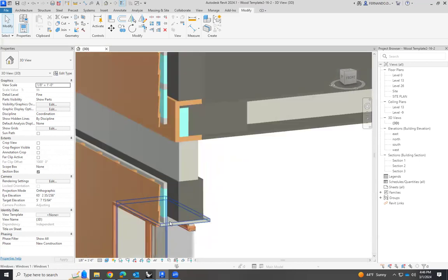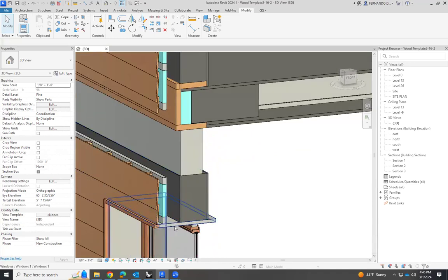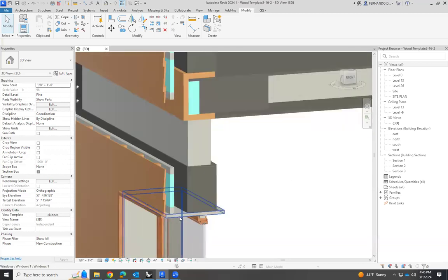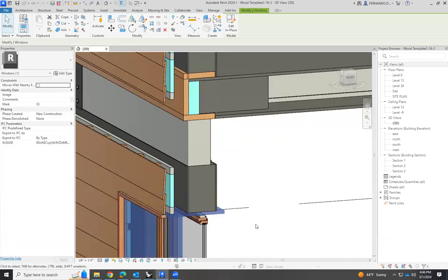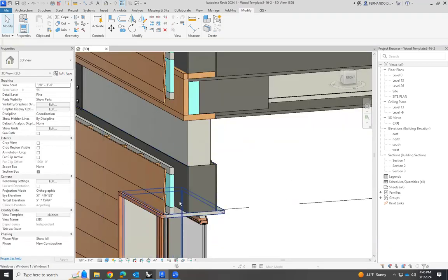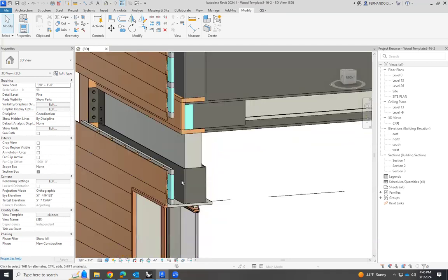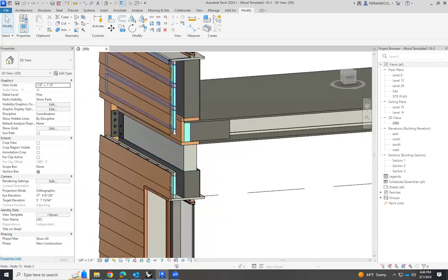But look at this, we have left this cavity, okay? So when we open the window, we use this element as a solid frame. So we can use this base to fill this with thermal insulation, and then we will cover the beam. The beam is the thermal bridge in this case. So we can do it.